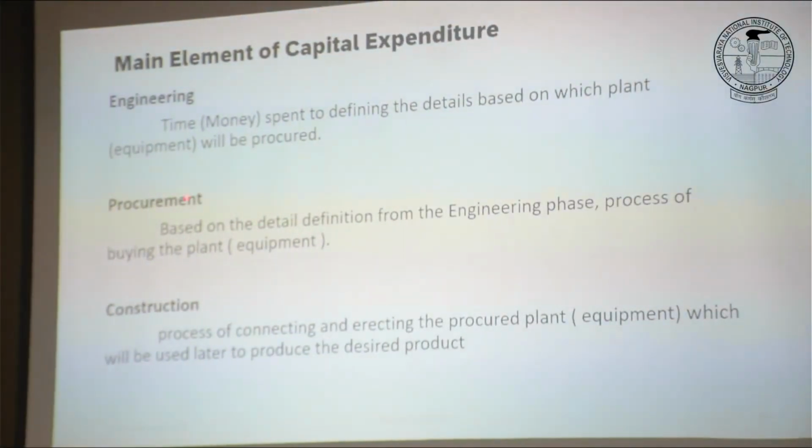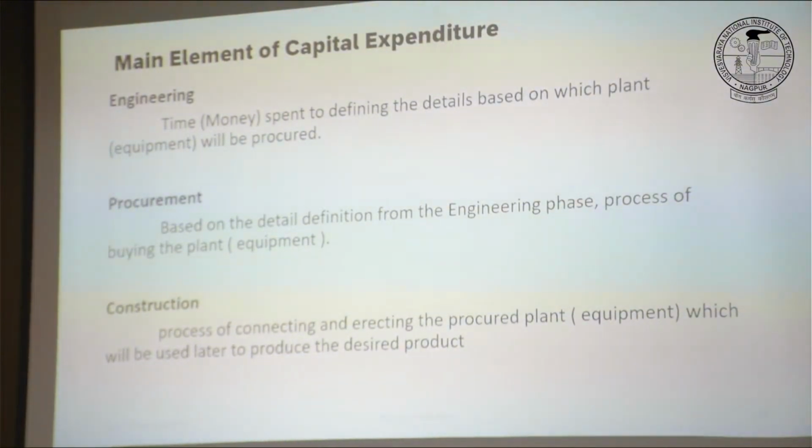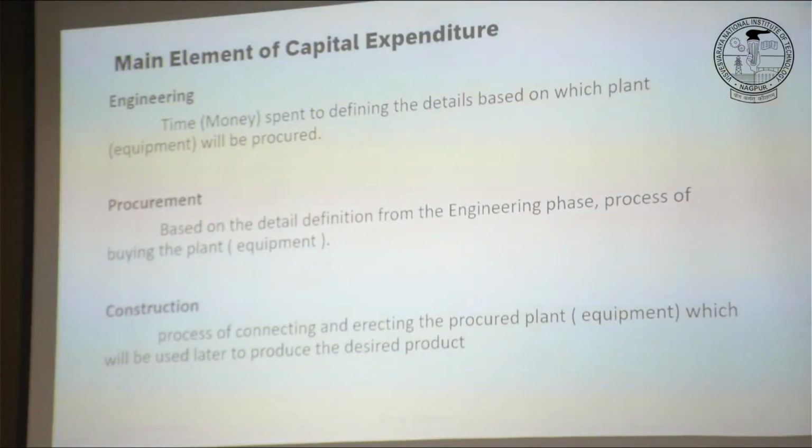Now, elements of the cost. We took the estimated weight of the metal, multiplied by the unit rate of metal, and we applied a factor of 50, and we had this cost, right? From this one equipment, we applied another factor, and then we had the total installed cost or the EPC cost. I'll explain what exactly EPC is, but the total installed cost of the plant, right? What exactly is in this total installed cost, we can categorize in 3 different parts.